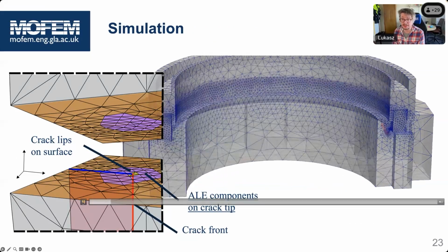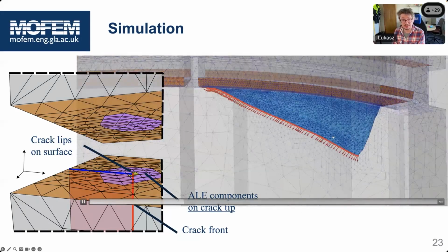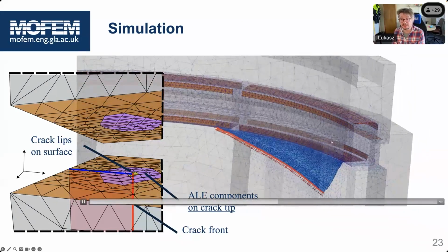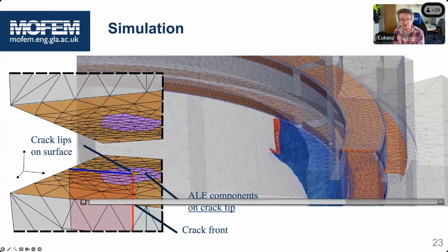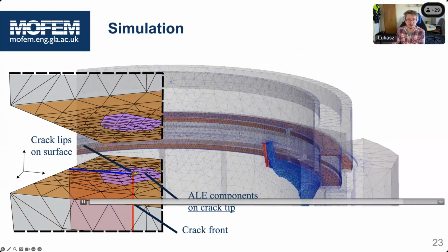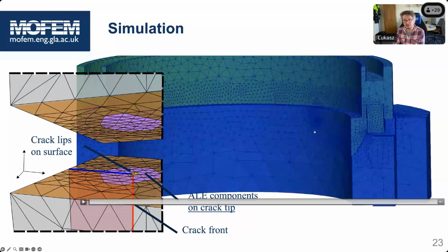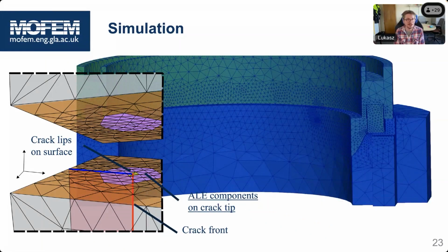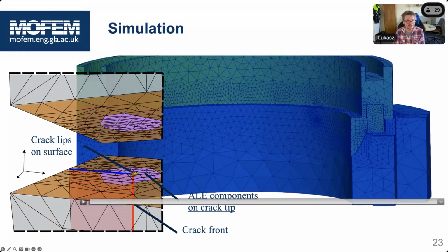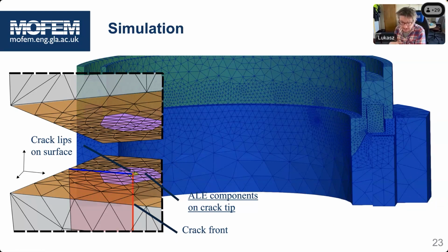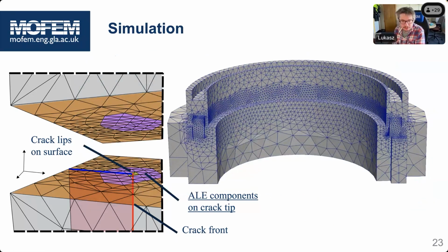This is a part which has a complex crack geometry with many contact surfaces. And on top of that, because we evolve the topology directly, we have to manage the complexity that the crack front is on one contact surface, not on another, and those nodes are moving. That leads us to the problem that we cannot scale, and we start to think about different solutions.